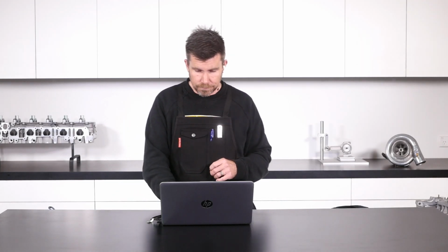Samuel has asked, where's the best location for an exhaust manifold pressure sensor input for a naturally aspirated engine? Is it somewhere on the header collector? Yeah, I would be trying to put that on the collector itself, or probably somewhere just pre-collector. Sometimes where you can physically fit the sensor, or fit the takeoff for the sensor, will be the other aspect.